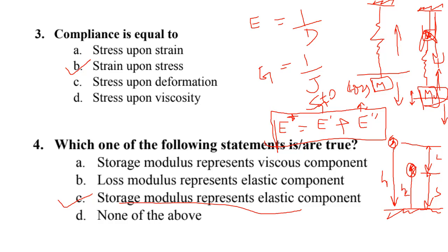Yeah. So basically, we have bearings for that reason. Like, if we want to isolate two structures, suppose the ground structure and the upper structure. So suppose there is vibration at the ground, and we don't want the vibration to transfer to the upper structure. Then the connection will be in the form of a bearing, and at that place we put a bearing, like a spherical bearing or something like that, so that the vibration transfer won't happen.